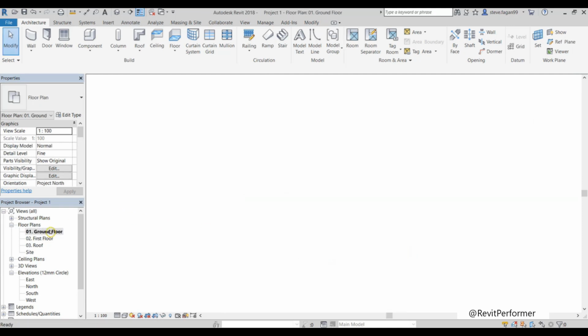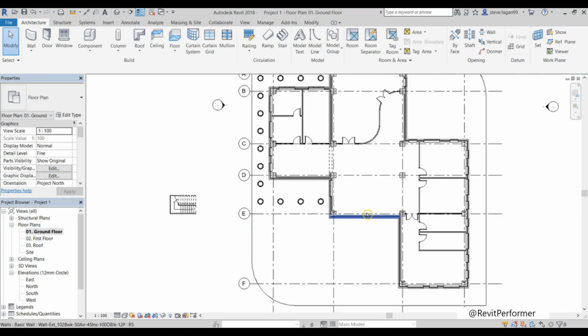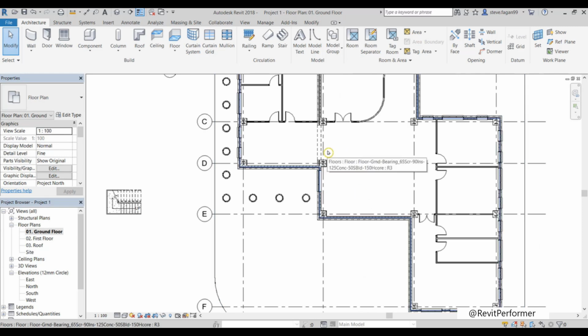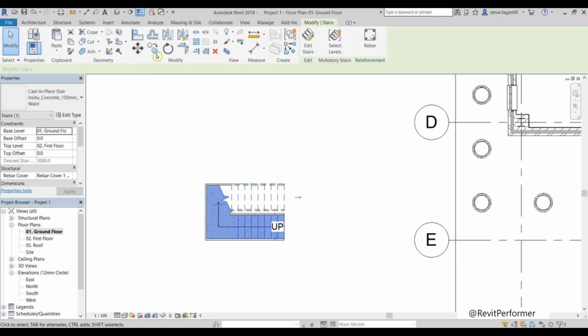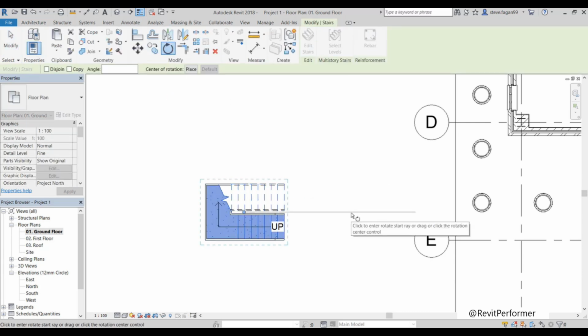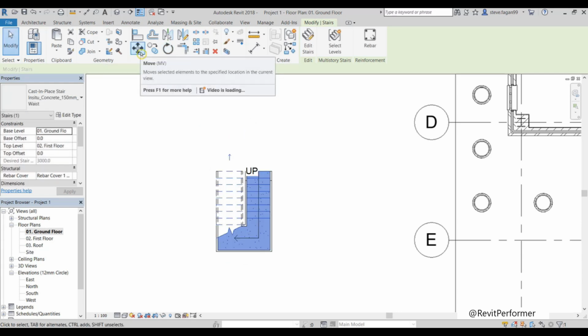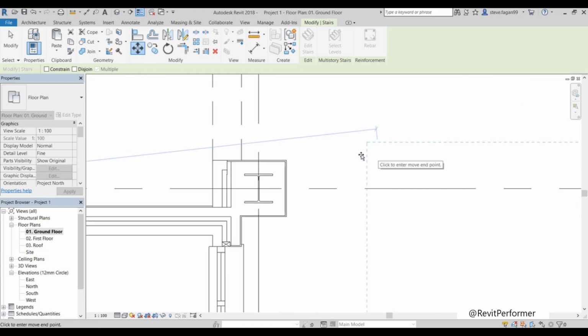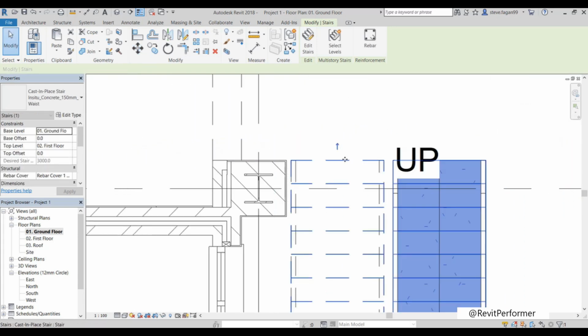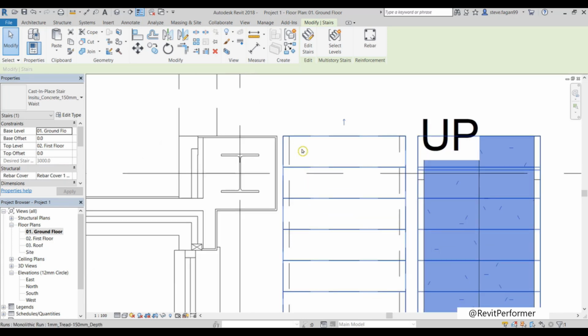So we're just going to place it. So open up our ground floor. The location of the stairs will be at this point here. If you open up PDF 012 stair location, first thing I need to do is to rotate the stairs. So clicking on the stair itself, the rotate tool, my start point, and finish. And using my move tool, snapping to the top left-hand corner, dragging it over, and hitting the upper right-hand corner of that column.